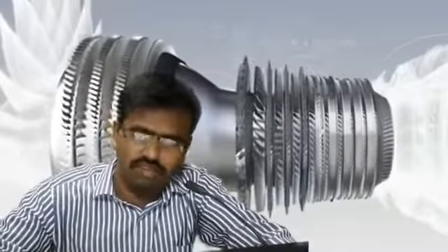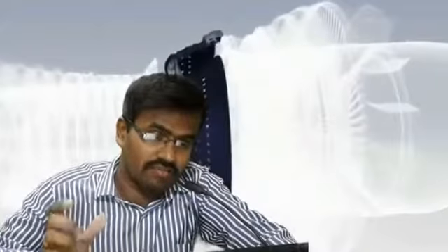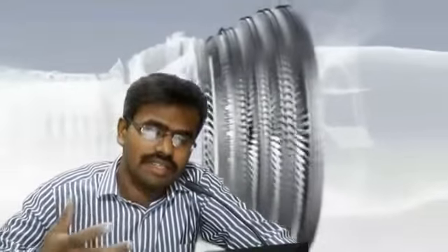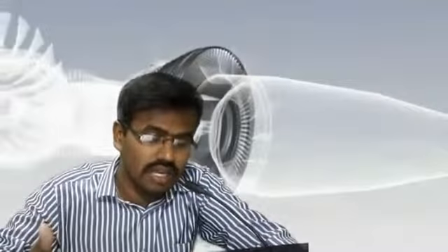The first type is the ramjet engine. Here is the drawing for the ramjet engine. First we have a subsonic diffuser, which is the first stage of this ramjet engine, right? Now the air enters the subsonic diffuser. The forced air from the surroundings, or from in front of the engine, enters the subsonic diffuser, and it is given to the combustor, or combustion chamber.